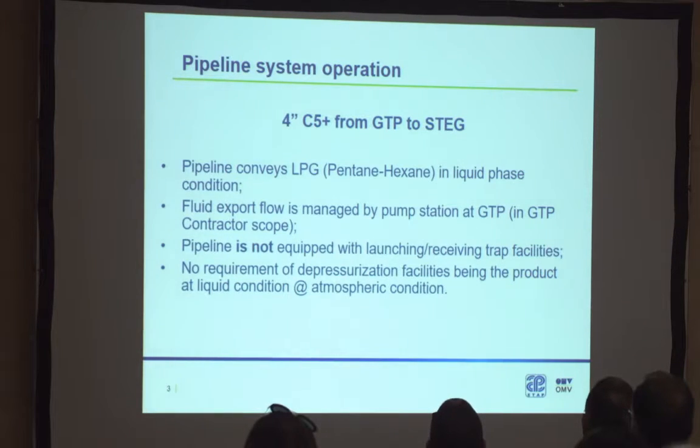This is the new pipeline for the condensate, stabilized condensate. We have a pump to export the stabilized condensate from GTP to the LPG plant. There is no pig launcher and receiver. No requirement for depressurization in this case.